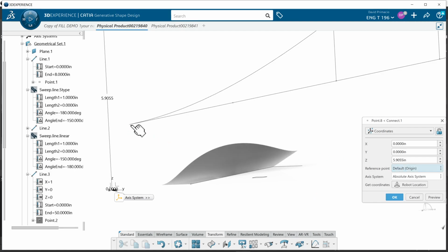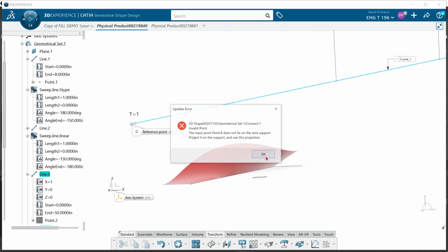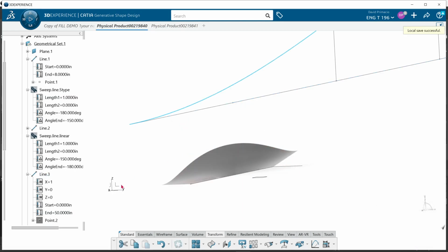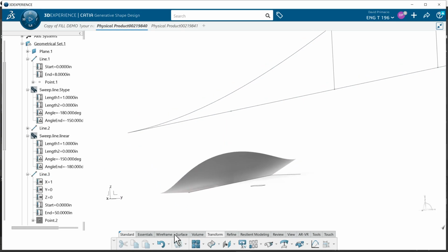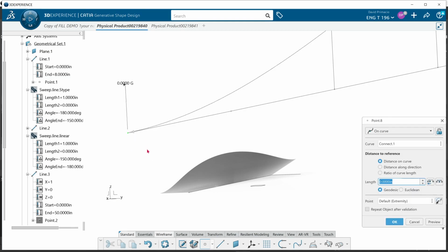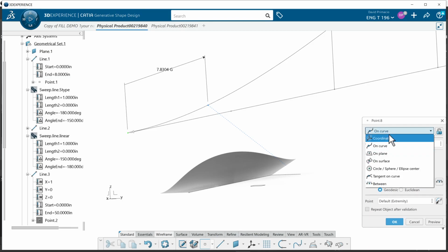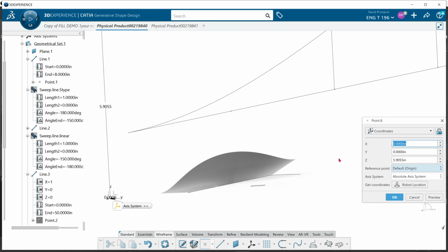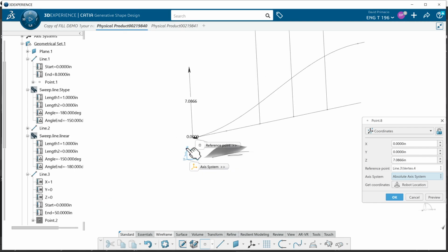And the origin point is going to be from this point over here, and the Z direction is going to be 180 millimeters for 180 degrees. Oh, it's not. Okay, you don't like it. I get it. All right, so let me just create a point from this line, from this point, 180 mm for millimeters. Okay. Select OK.